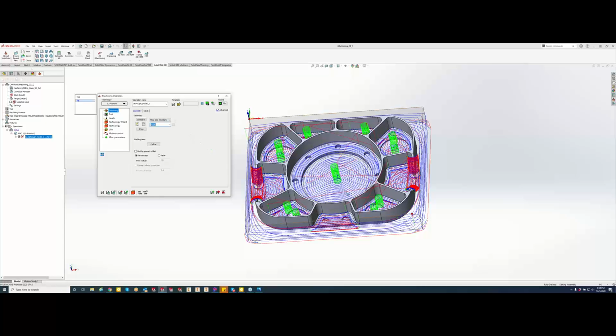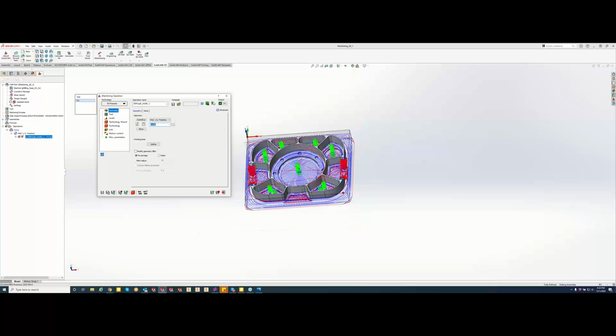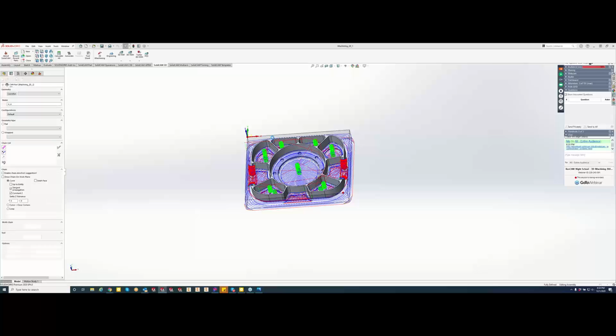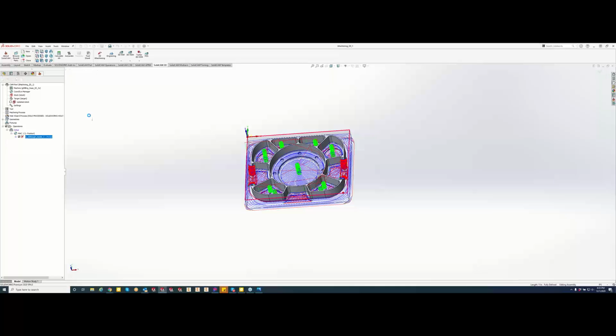And so what Greg is saying is, let's say we had 4 of these parts on the line right here. Even though we only have selected the one model, iMachining is going to see those other ones as stock because they are listed as your stock in there. So what Greg's getting at here is, if you had 4 of these parts, come in here, do your working area, and then just chain it up like anything else that you guys have done before.